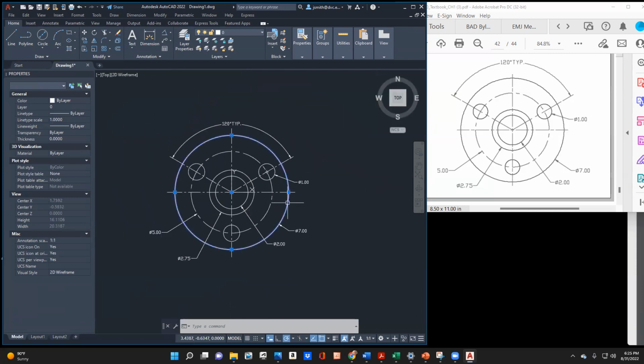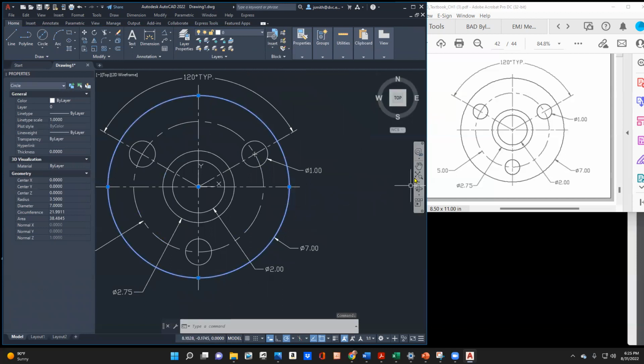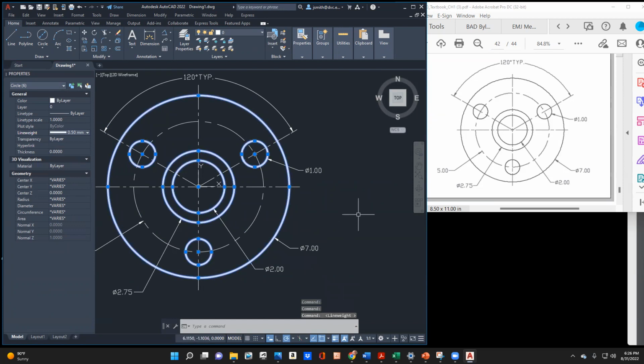So what I would do now is I would want to make sure that a part like this, that my line weight's typically the outside of the object. The drawing doesn't really differentiate all that much. So typically the parts of the drawing would be thicker than everything else. So I would go into line weight. This one, the drawing doesn't show it all that clearly, but generally the parts are always going to be a little thicker. Come down here and make sure it's turned on.